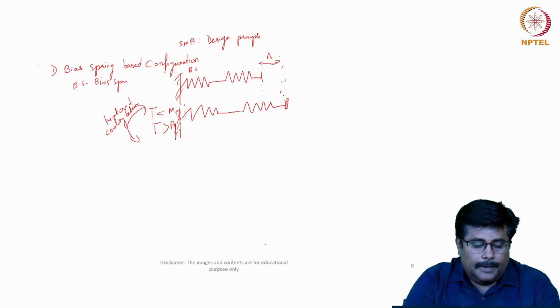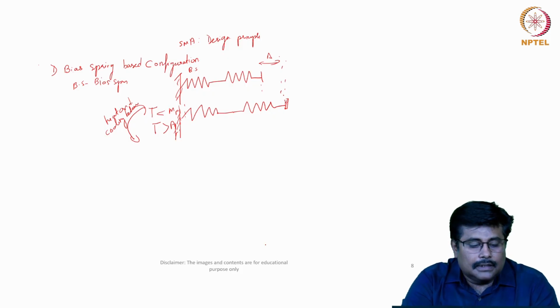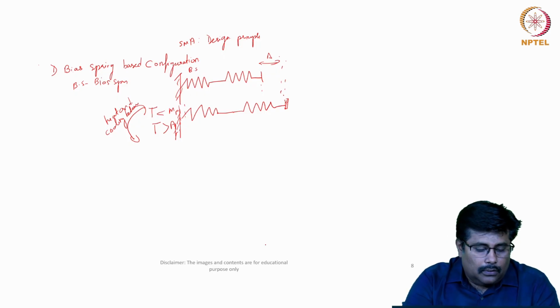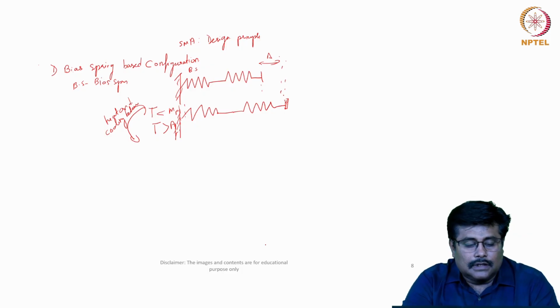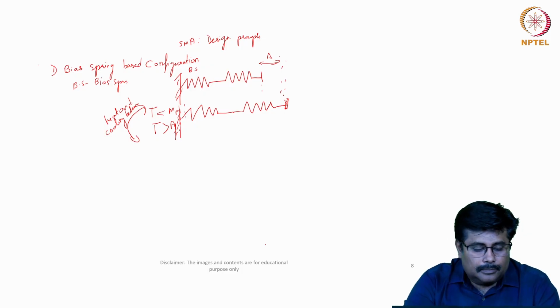Upon heating, the material tries to regain its original shape. Martensite turns into austenite, resulting in an increasing force towards the SMA spring, which we call state 2. On cooling, the martensite variants nucleate, but instead of being homogeneously distributed as in the case of stress-free cooling, they orient themselves so that the stress resulting from the pulling force applied by the spring on the SMA is minimized. As a consequence, the equilibrium shifts towards the bias spring at this time.